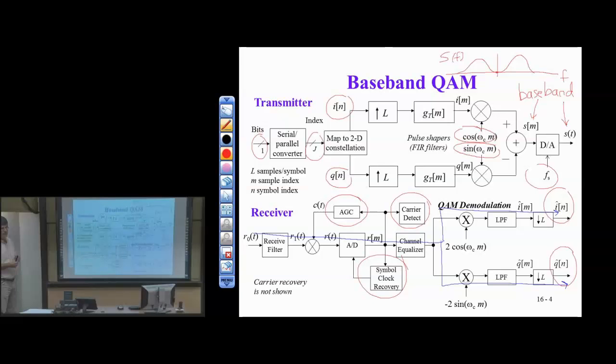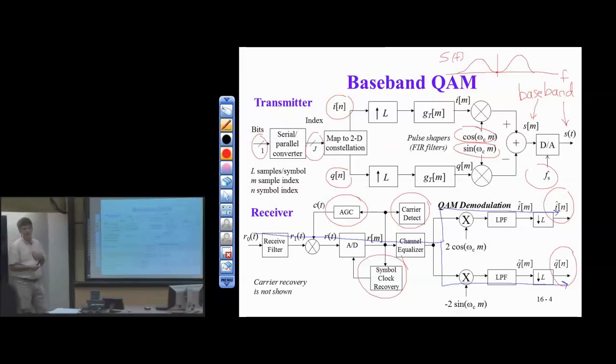Adaptive. Yeah, FIR. So we can do adaptive infinite impulse response filters, but what do you think the problem is with adaptive infinite impulse response filters? Stability. So for here, maybe a long time to train, possibly. Bigger problem, stability. All right, so adaptive IIR filters do get used in practice in some applications, but rare in this case. We're commonly using an FIR filter. Again, stability is the big issue. So there is a subsystem off to the side not shown here, which is to design those FIR coefficients. And we'll talk about that design today.